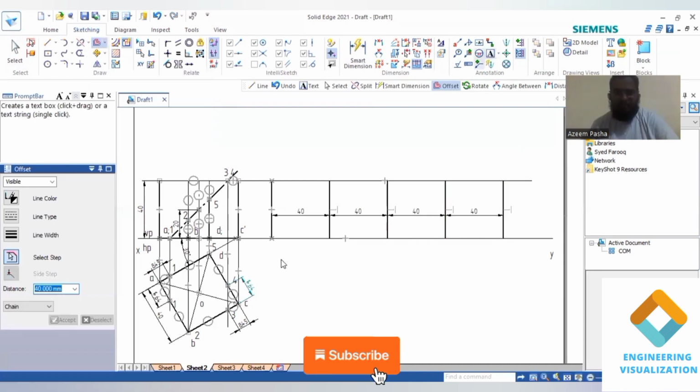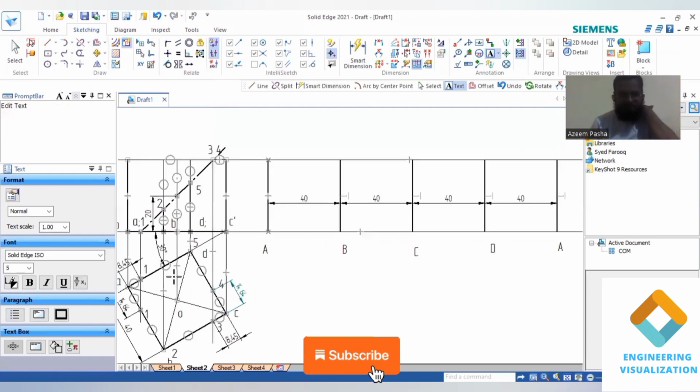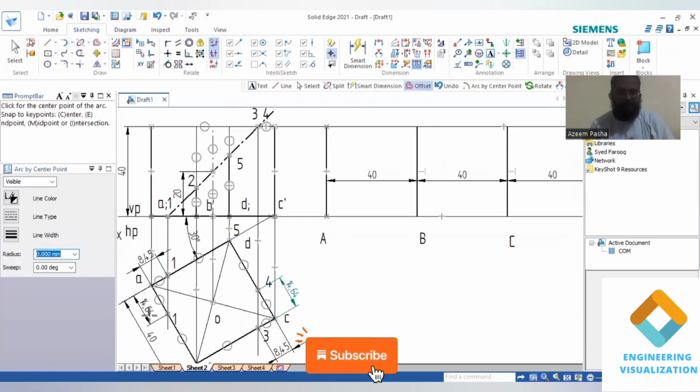Now we can mention the naming for it. It is capital A, capital B, capital C, capital D, and capital A. And now we need to mention wherever we cut the section plane with the number, from A to 1 on the line AB it is 14.64. So I'll be taking arc by center point from the A point. I'll be measuring the length of 14.64 and cutting the arc. So cutting the arc, this is your point number 1.